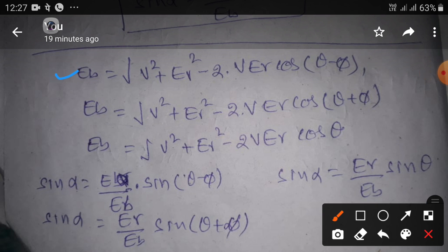That means the terminal voltage is greater than EB, the back EMF developed in the stator. During this period, the armature current lags the voltage by some angle phi, that is, we say lagging power factor. This is the armature current, this is the voltage.